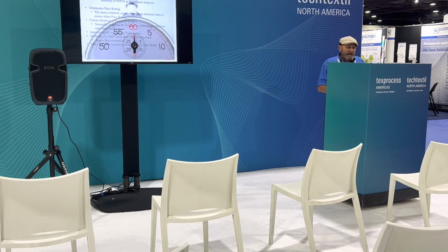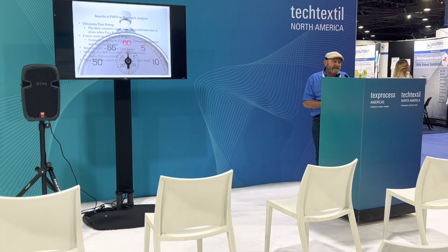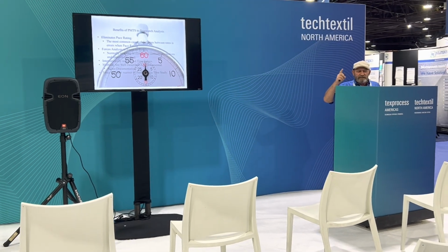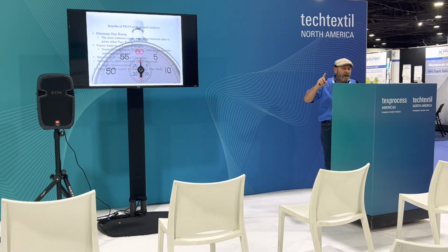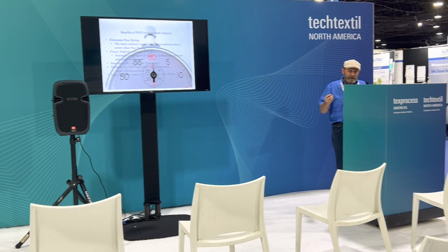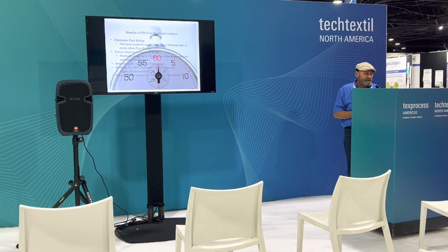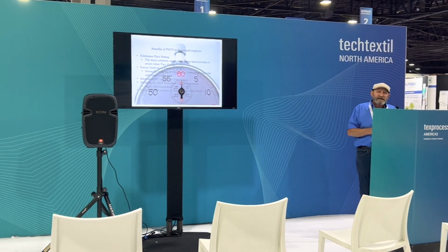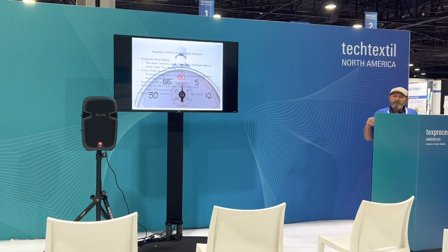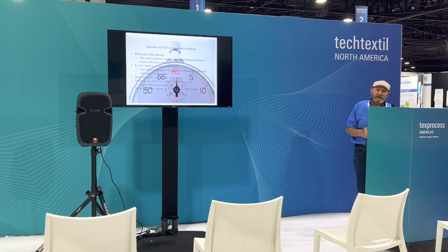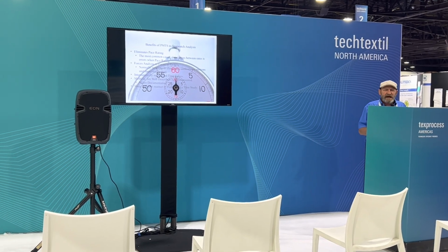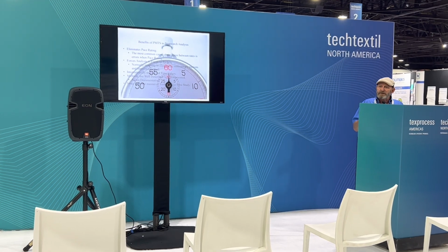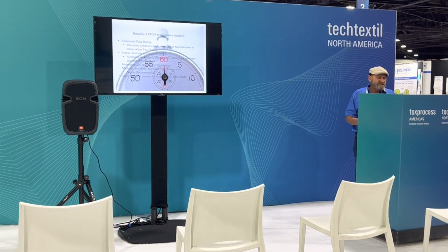Okay. Benefits to a predetermined time system over using a stopwatch. It eliminates pace rating, as I already mentioned, which is one of the biggest problems you can have when you use multiple engineers to set production rates. It forces the analyst to pay attention to the details, which almost always leads to an improvement in your methods. And the time values that we use are accepted as international standards of what 100% pace is.